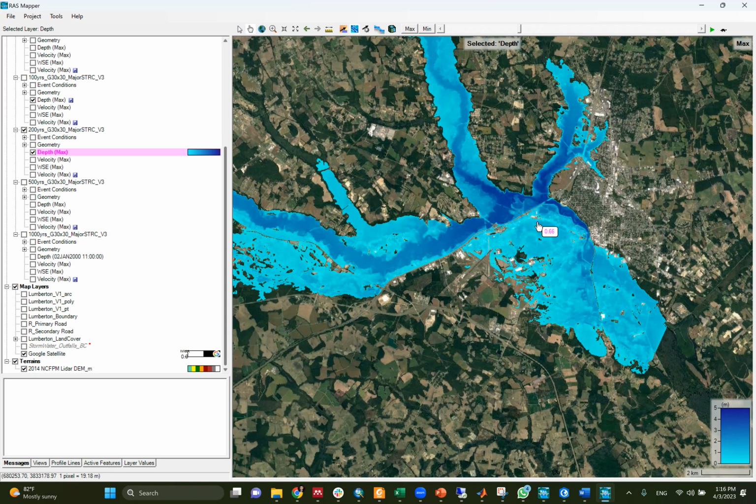You export the water surface elevation map, WSE, out of HEC-RAS, or I will give it to you for your project, and extract the water surface elevation at each building. And what you will do next step, you will have in your ArcGIS a field